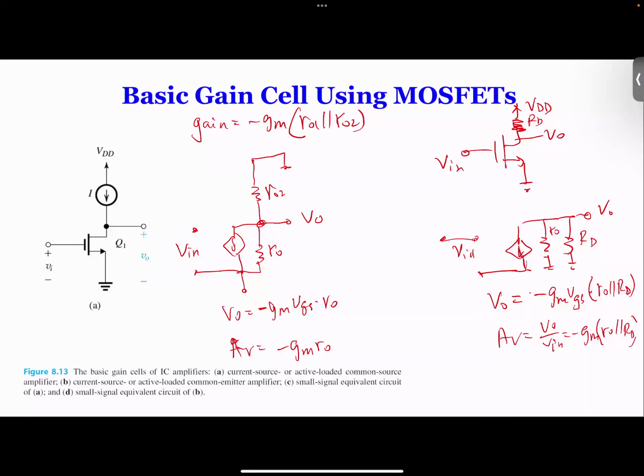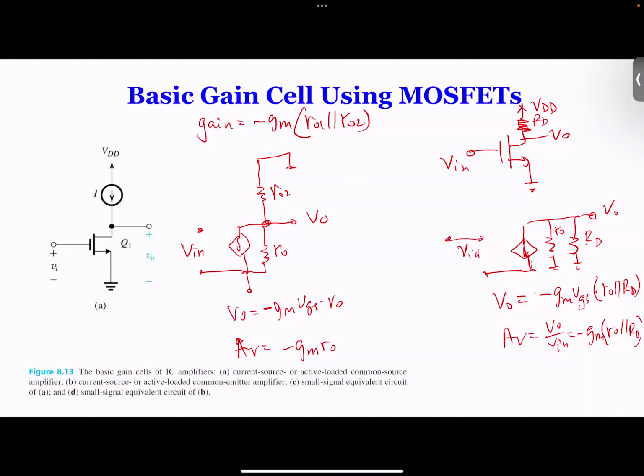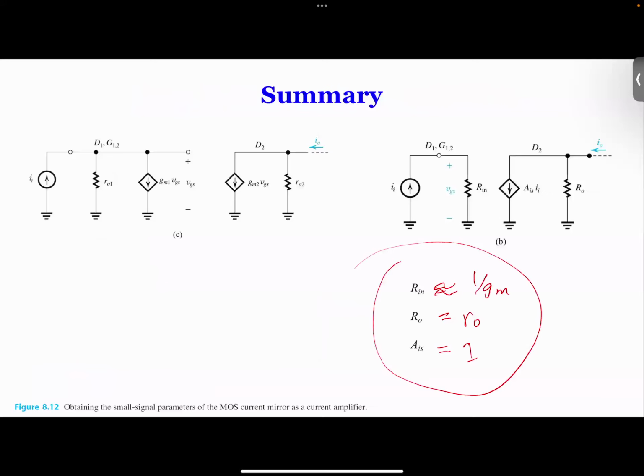Yes. What is that? What is the constant value? No, the constant value RO2 is what we derived. It is the early resistance of that ideal current source. If I go back to show you what we had here, see here, we had RO, which is RO2, exactly this one here. Yeah, that's the current source we got.